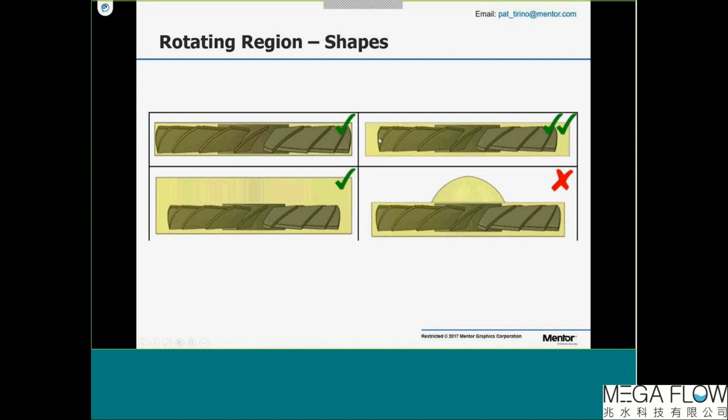Here is better because you're giving the flow some space to come off of the effects of the fan. Basically some space to extend itself, for extension. So that's always good there. There's always a reason for that. Something like this, there's no reason to make a shape here. It's just not necessary, and it may cause more issues than it's worth. So no reason to make it detailed to this effect or add a shape that's not there. It just doesn't make sense.